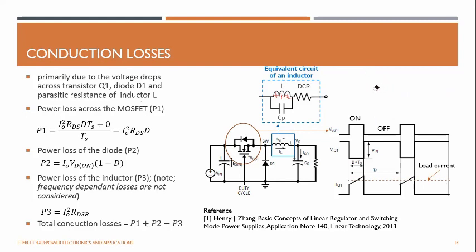That is called parasitic capacitance, and it makes an equivalent capacitance in the picofarad range, a very small value. But for the power loss, the contributor is this DC ESR.